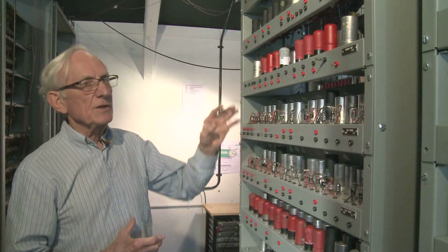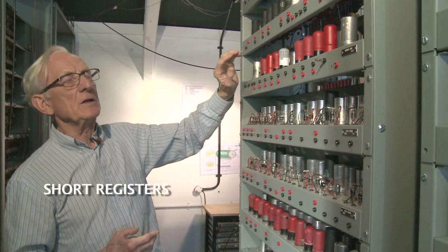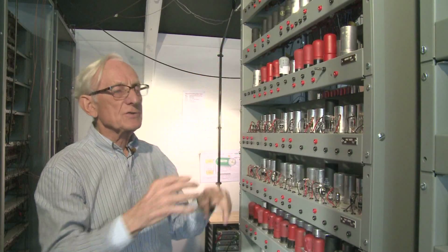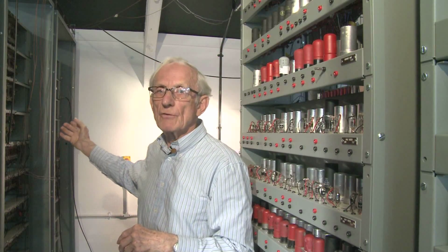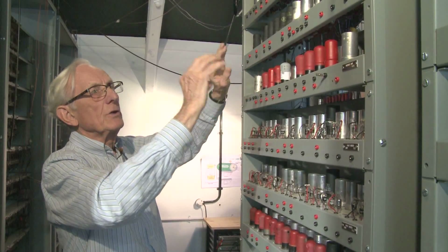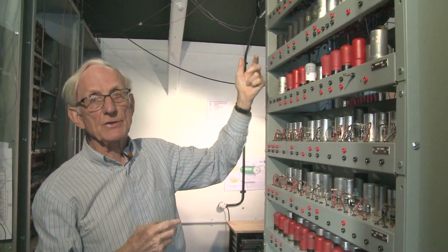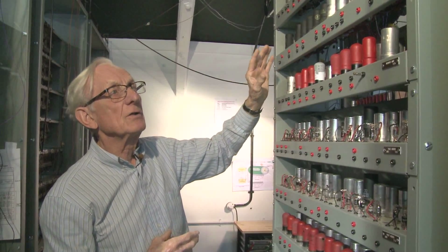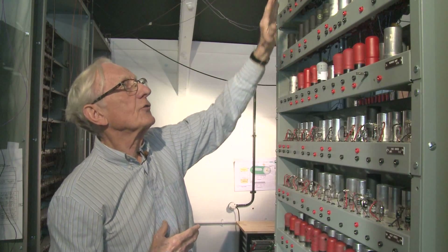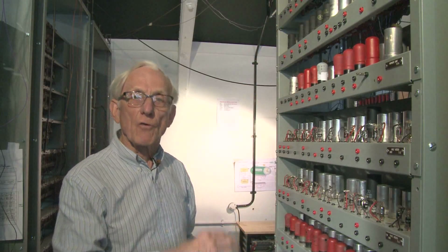Now, to assist in that, this equipment has got 3 important key registers holding short numbers. These are little memory tanks, similar to the ones we've been talking about for the main memory, but they're short tanks which only hold 18 bits in this case. In fact, there are 6 other tanks in the machine, mostly in the arithmetic unit. So as well as the 32 long tanks, we've got 9 other shorter tanks, 3 of which are here, and they're the main primary registers for control of the machine.